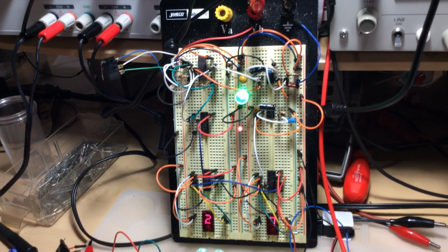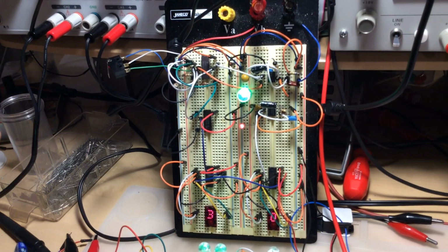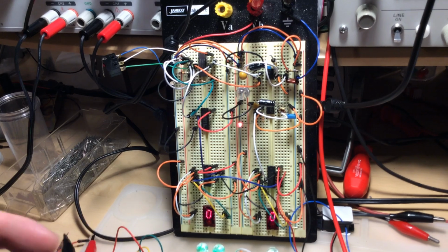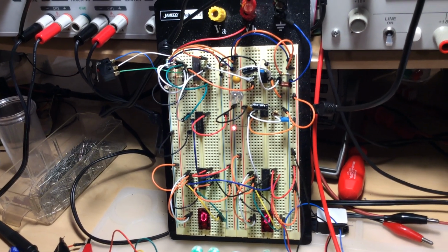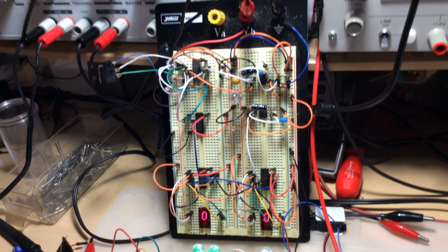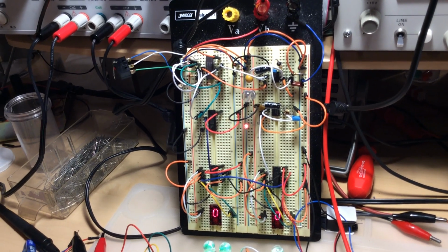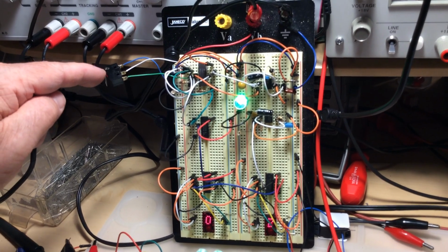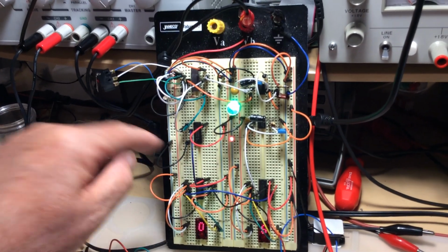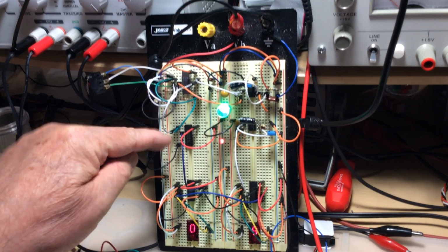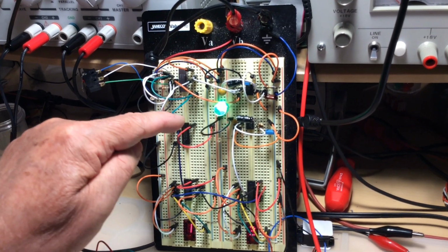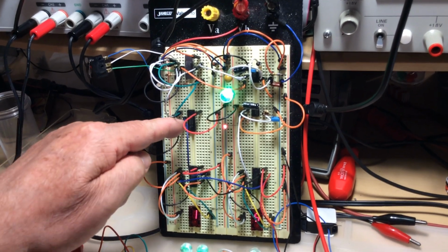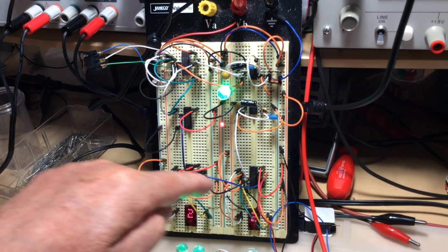So this is the meaning of using the OR function. You cannot put the 2 resets together because if they touch each other, take a look, 35 seconds. If you put them together, they're going to interfere with each other. This is why you have to put each reset in the OR gate on one input each, manual reset on one input, automatic reset on another input. So this is my manual reset is going on one input. This is the automatic reset is going on another input. And then the output is going to go here to reset the packages.